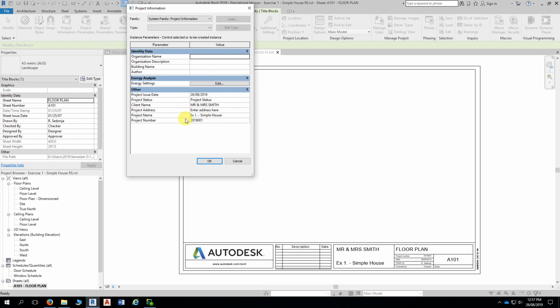So if you were undertaking a project where you had several sheets, and this will happen in Revit Intermediate where we are producing 9 sheets, what you would do is you'd go straight to Project Information and you'd put the information in here, and what would happen is that every time you produced a sheet, the information would be transferred to that sheet automatically. The only thing that's not put in automatically is you, as in drawn by.